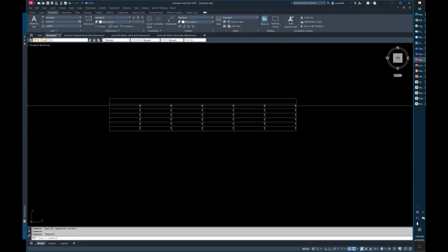All right, Mark, you have issues opening drawings. I can see the preview. When I try to open it, I get a window that says drawing file is not valid. All right, there could be a couple of things going on. The first thing is you have to understand that there is a hard limitation in Windows for how long the file path can be, including the drawing name and extension.